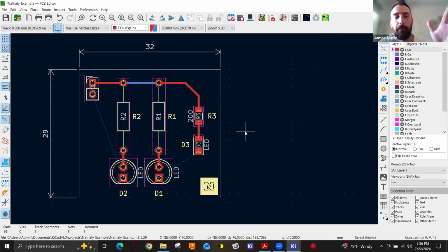It will pour copper all over the board, make direct connections to your pads, and avoid all your other nets. It seems kind of weird, but it's a really good thing to do if you need big connections with lots of current, like I was talking about earlier. Since all of your currents typically return on ground, you normally need a lot of current flowing on ground, so you tend to do this for ground.